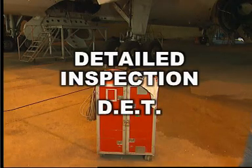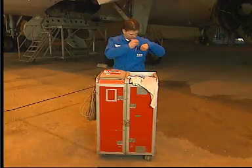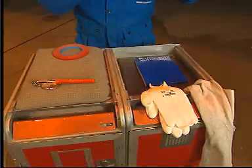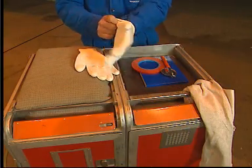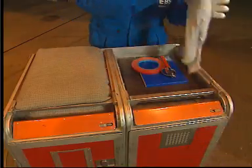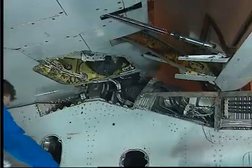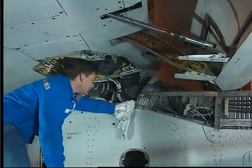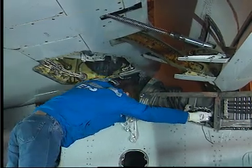Now let us explain the Detailed Inspection (DET). The Detailed Inspection is an intensive examination of a specific item, installation or assembly to detect damage, failure or irregularity. Touching the item to inspect is necessary to help the inspection. Consequently, do not forget to protect yourself with gloves.